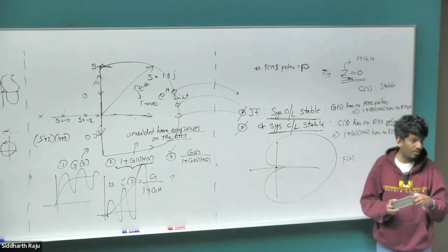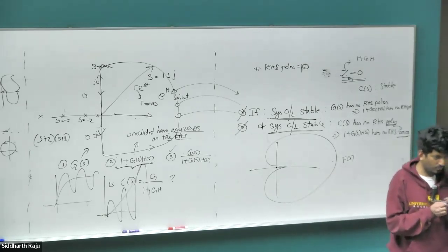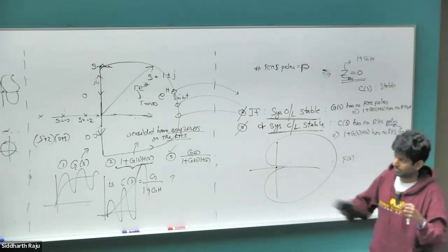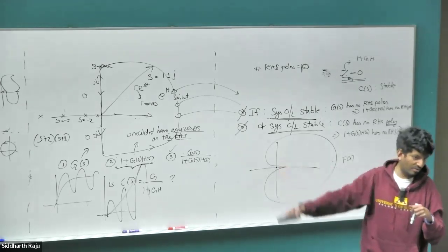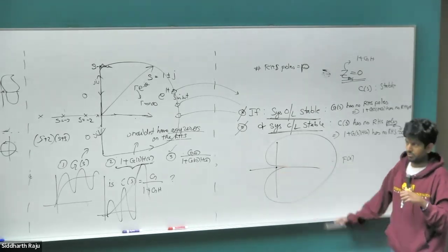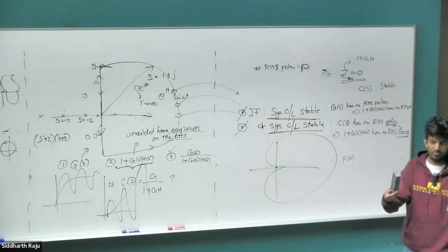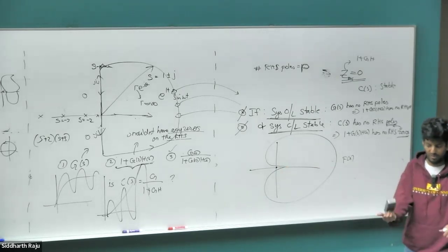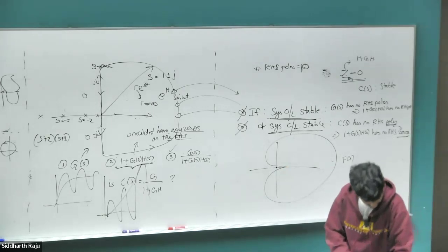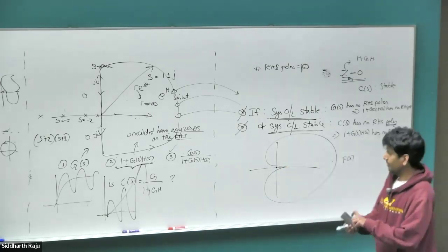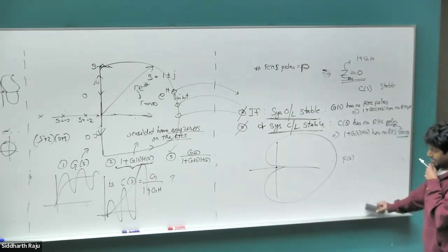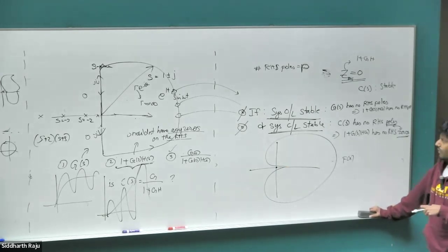Can you be closed loop stable without being open loop stable? Oh yeah, that's the example that I have right there. 4 divided by s minus 1: open loop unstable, closed loop absolutely stable. Inverted pendulum case, right? You have something unbalanced, but I can balance it. I'm very poor at it, but you get the idea. Any other questions?